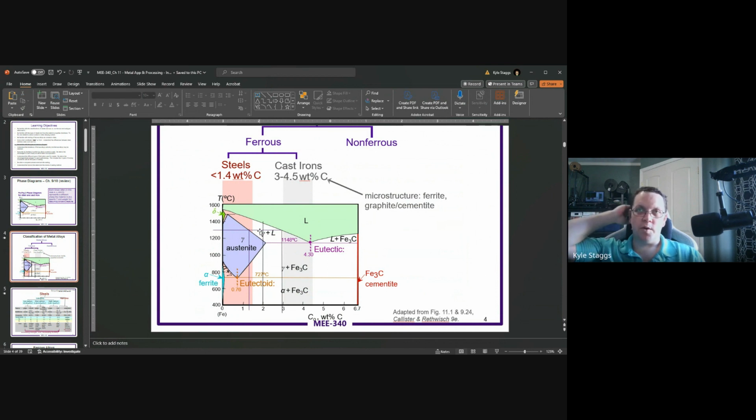Because if you're looking for the weight fraction of one thing, you calculate it very differently than you do for the other. So R over R plus S versus S over R plus S is the answer to two completely different questions, and you need to really pay attention to what you're looking for, what you're calculating. And then some of you came up with like a 350% composition or something, which was very impressive, although utterly non-physical. So that was pretty interesting.